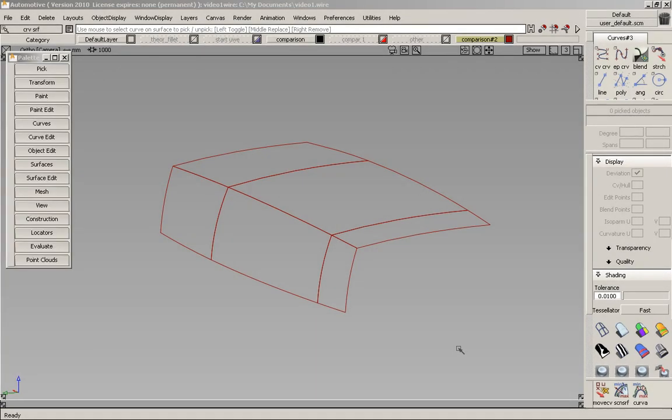So what we have here is the data set from section 1. So if we want to build a fillet or a blend in here along this theoretical, we do have some traditional methods that we can use to do this. One of them we reviewed in section 1, which was the variable radius surface fillet. The other one was Freeform Blend. And now we're going to use Tubular Offset to set our radius in here to get a curve on surface. Once we have a curve on surface, we can trim the surfaces back and build our blend.